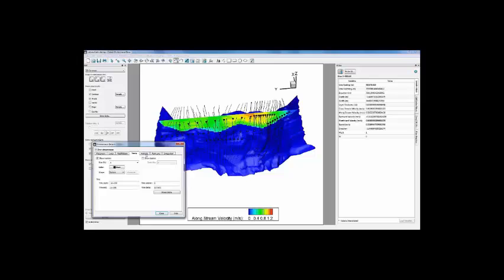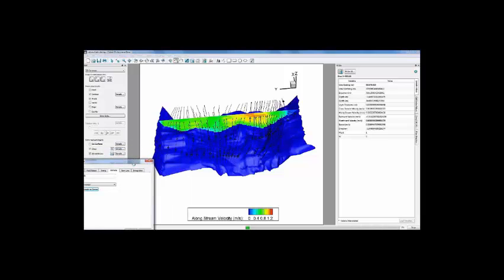Yes, streamlines and the ability to do this is something we've used for a long time just to qualitatively understand what's happening. Where do I have areas of secondary circulation? Where do I have helical flow? Where do I have eddies and so forth? Looking at the dispersion. The ability now to take something like this and overlay it, we have our bathymetry here, and the streamlines make sense with the bathymetry we see.